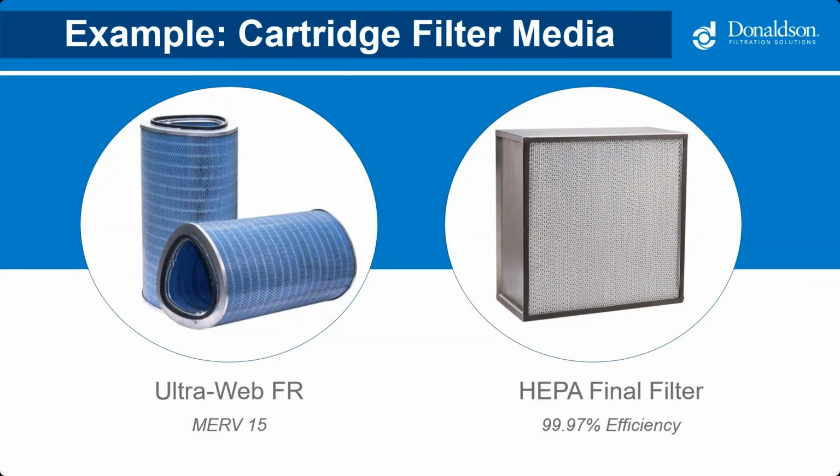And then also, as mentioned a couple slides ago, in most cases these dust collectors are located indoors, and depending on the material being cut, the exhaust returned to the facility and the dust could be considered toxic. Such dusts include, but are not limited to, aluminum and stainless steel. In these cases, we would recommend a HEPA afterfilter, which are 99.97% efficient in capturing.